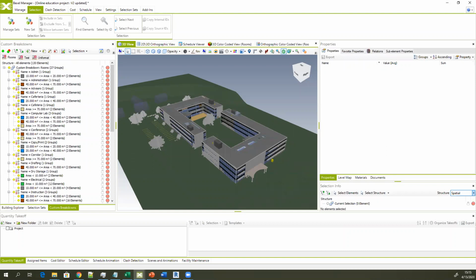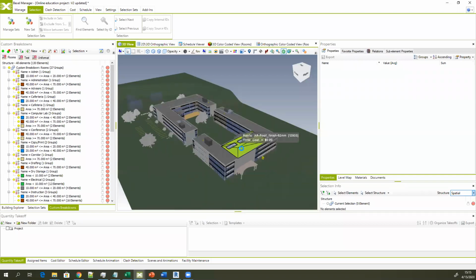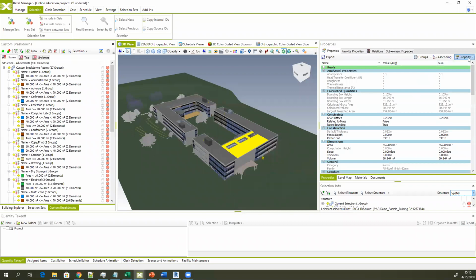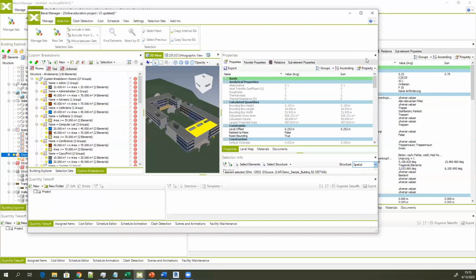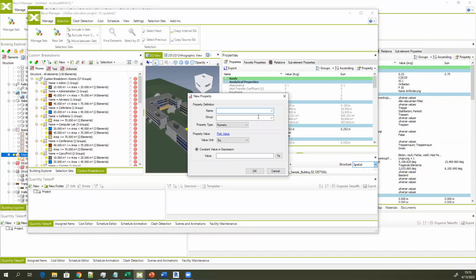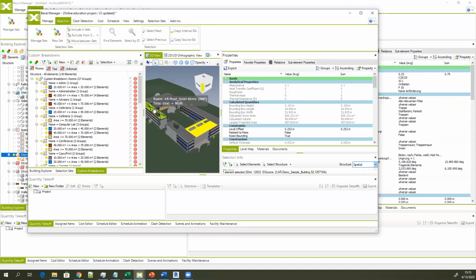How will the newly added properties be exported to IFC? In which class of IFC? Well, if you're just talking about the properties, they will be exported in the same way as you added them. You're adding a specific property type, specifying whether it is numerical, length, area, textual, or a different type of property. So these are going to be mapped according to that automatically.